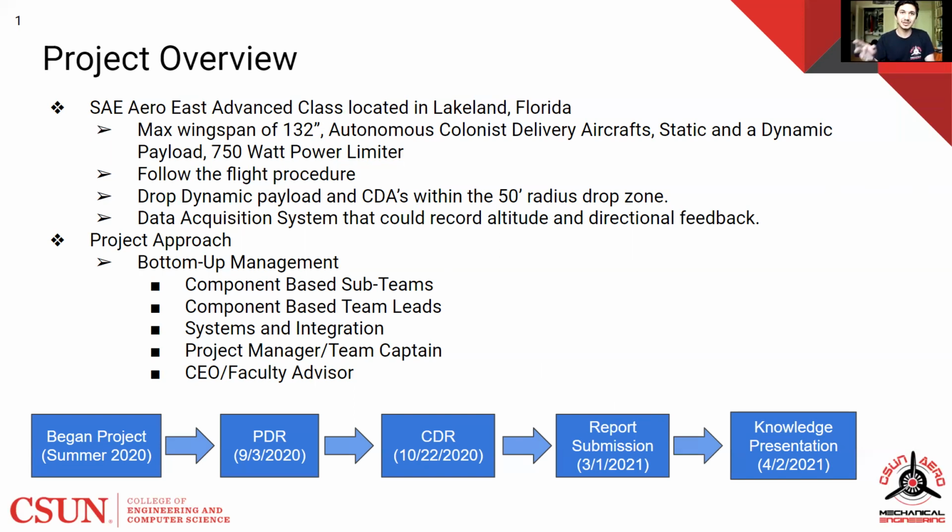Initially it was more about how we can maximize the amount of lift we're generating for the wing. But then we added manufacturability, since we knew we were trying to outsource it and couldn't find a place, so we would have to build it ourselves. So we opted to add manufacturability as one of the main considerations for the airfoil. The 3 that we went through for wing consideration were the Eppler 423, the S1223, and the GOE 447.